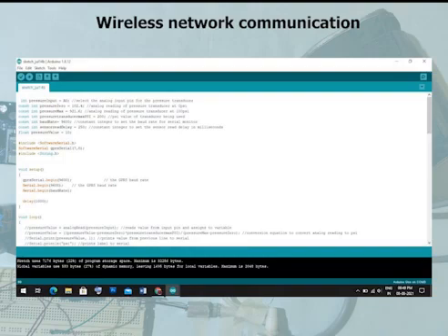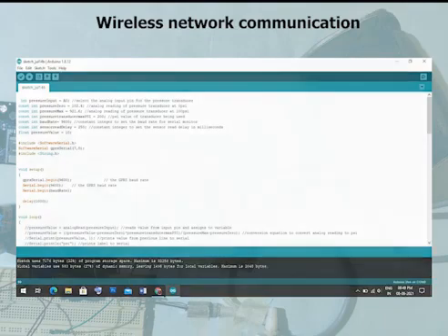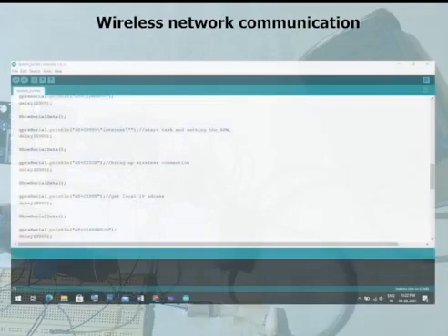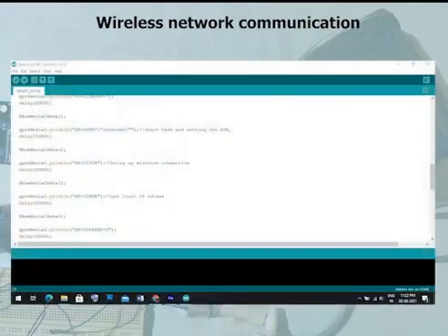The obtained pressure sensor value is stored in a variable called pressure value. To push this value onto the cloud server, we need to establish a network, in our case a GSM 2G network. To establish this network, we make use of AT commands which are used to establish a network using a cellular device. After all the necessary commands are called, an APN is set up to enable cellular connection.